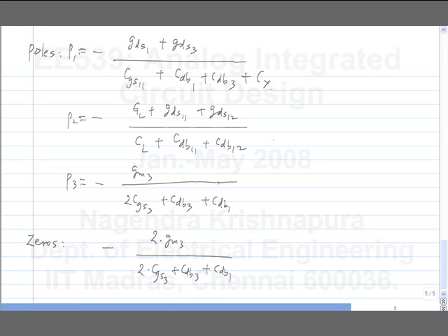That depends on other poles, right? If you don't have any other poles, I don't care about making it very large, making Cx very large. So roughly, yeah, P2 by 2. Maybe I will say that the parasitic pole has to be twice the unity gain frequency or 1.5 times. Whatever it is, it has to be beyond. So I have to make Cx large enough so that the resulting unity gain frequency will be below P2. Okay? So P2 is in fact the limit on the unity gain frequency. Similarly, if I choose to make this lower, what is the limit? P1, obviously, right? Now, if you look at it, so P1 or P2 will become the limit on the unity gain frequency. What was the unity gain frequency of the single stage amplifier? GM1 by CL. Okay. So if you compare it to this quantity, P2 and P1, are they lower or higher?